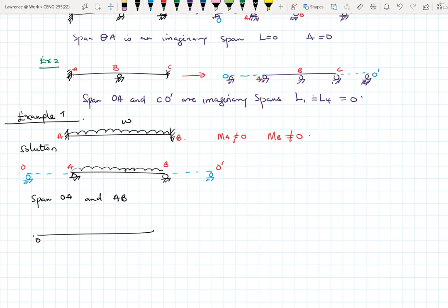So my bending moment diagram will be like that. This is OAB. Because between O and A there's no load, there's no moment. I'm trying to draw it to look like it has a length, but in reality it doesn't have any length. So let me just do this as short dash lines, so at least we see the difference between the two.